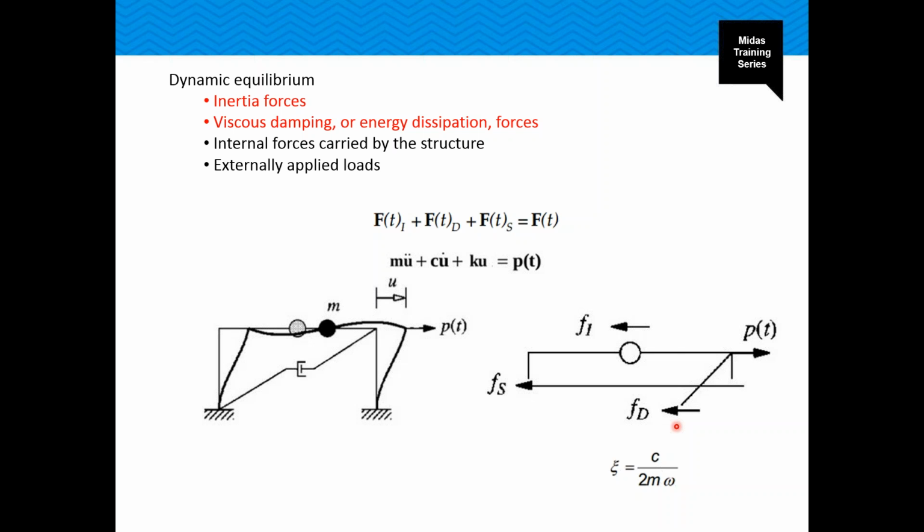In damping, the energy of the vibrating system is dissipated by various mechanisms. In a vibrating building, the energy dissipation arises from the internal friction when structural members are deformed. Also, friction at steel connections, opening and closing of microcracks in concrete, and friction between the structure itself and non-structural elements contribute to the energy dissipation.